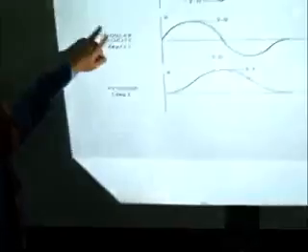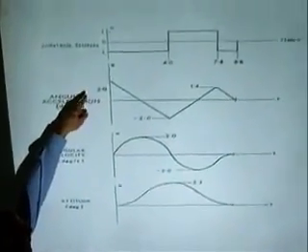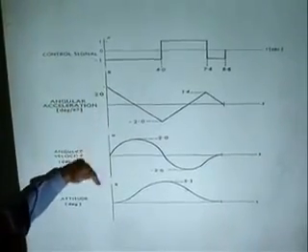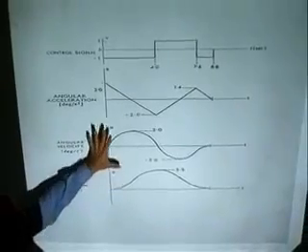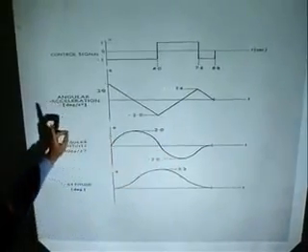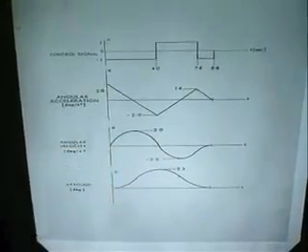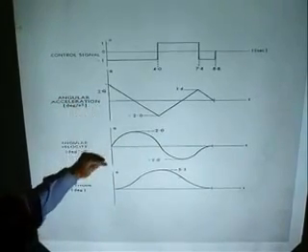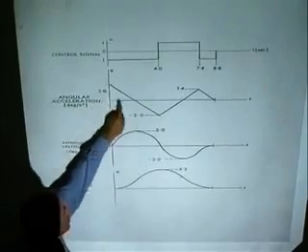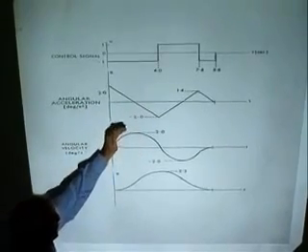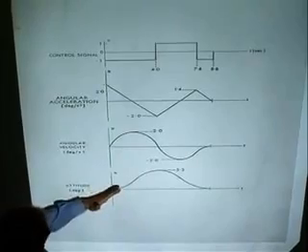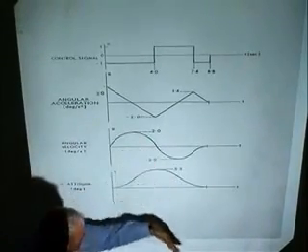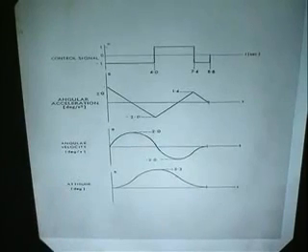So you'd get from that initial misalignment an angular acceleration, which had to be brought down, and the resulting rate and angle excursion, those two had to be brought back to 0. So it's accomplished by 3 periods of constancy, which brings down that initial misalignment, goes in the other direction to stop the growth of angular velocity, does what's needed to turn around the attitude error, and now bring them all back to 0 in the minimum time.